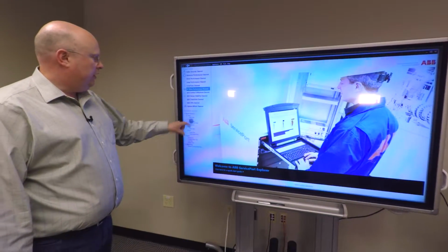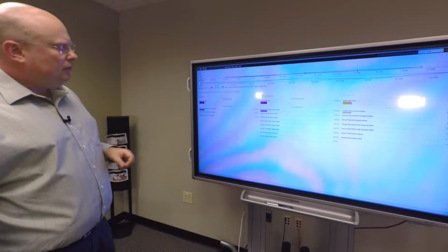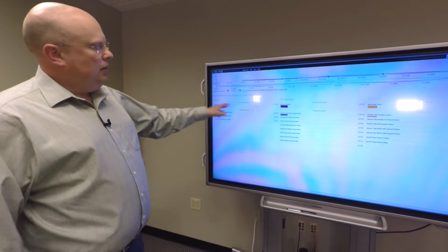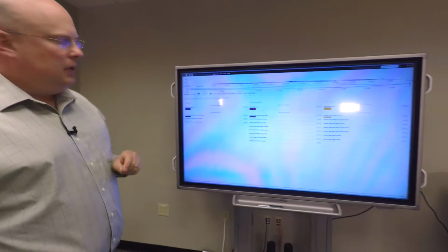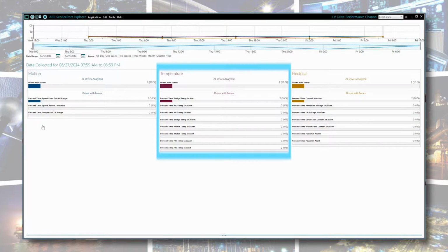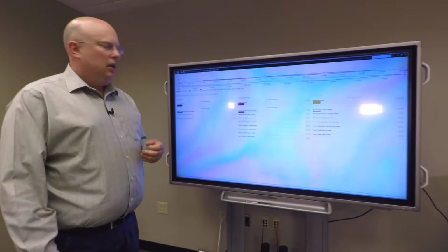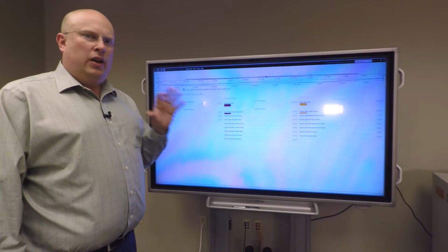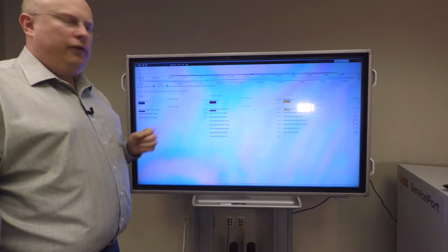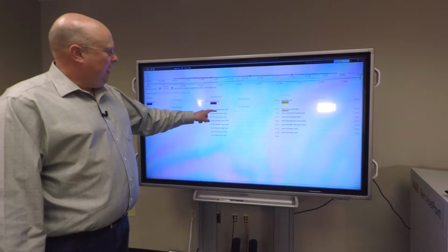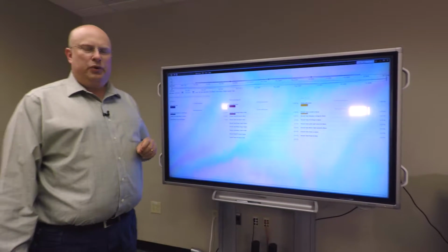So we start with the signal analysis. It will measure motion, temperature, and electrical. If you look at temperature, the temperature of the motor, the temperature of the frequency converter, and high temperature on any kind of equipment is reducing the life of that equipment. So it's important to not run things too hot because you shorten the life tremendously. So here we have the bridge temperature in alert.